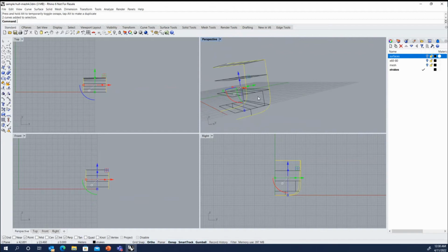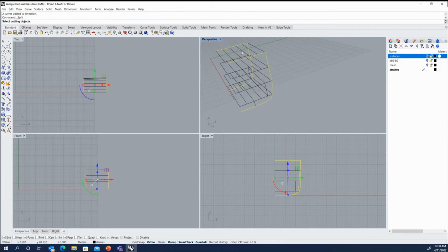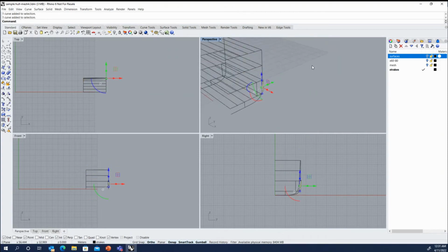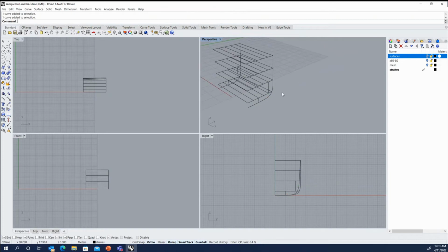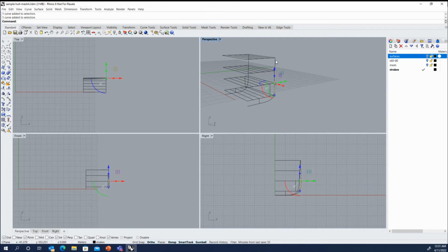I could specify a height and cut sections through these curves, or I might want to just do evenly spaced between each section in here. So what I'll do is I will use the split command, and I'll just click on this toolbar button over here. And those curves were selected, but I want to split at each of the decks. And now you can see I have separate small pieces of curve selected.